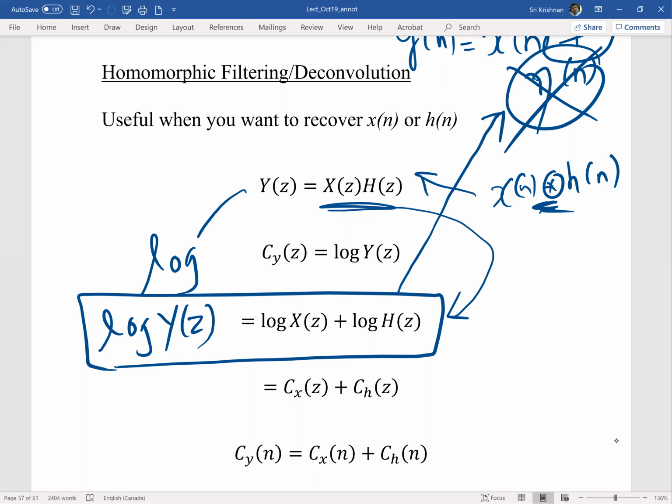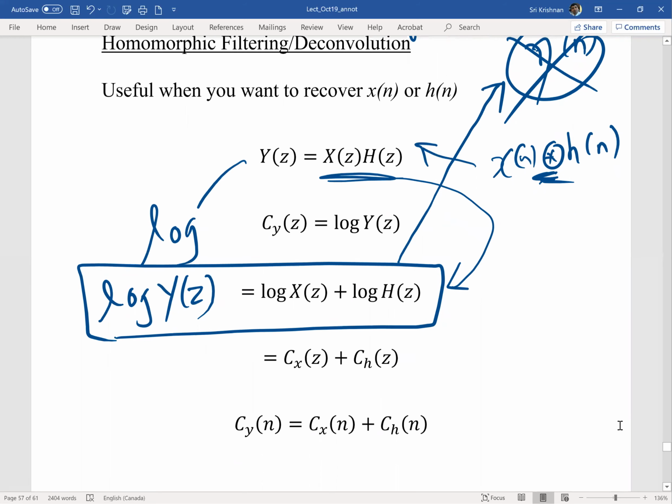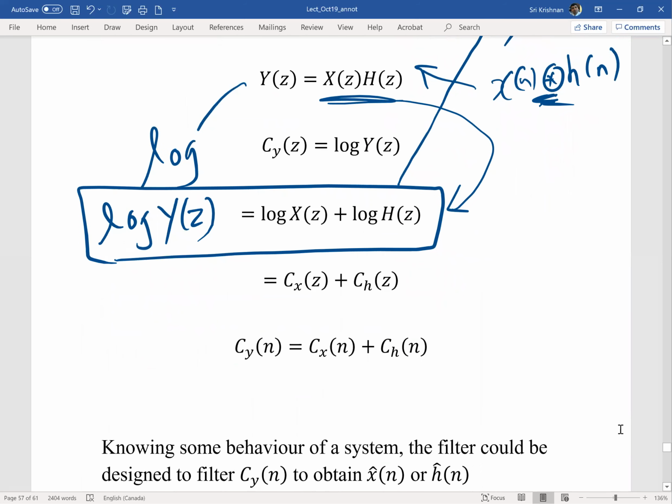That's where there's a little bit of mathematical trick, but not to be concerned. From a number representation point of view, if you're just interested in the magnitude response of the system, we can always take the magnitude and just work on the real quantity, which solves most of it. As we know, magnitude response will do most of the work for us, and we need not worry about phase response. So taking a magnitude will do the job for you, and you will get the equivalent thing in the magnitude domain.